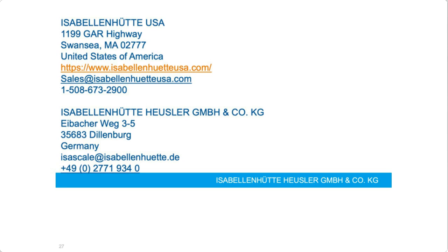This basically just refers to the other 3 voltage sensing channels that our product offers. So with the IVT 3rd generation Pro product, you get up to 6 high voltage sensing channels, and 3 of them have to be used in defined spots for the isolation monitoring to work properly, and those were the red dots on this slide.